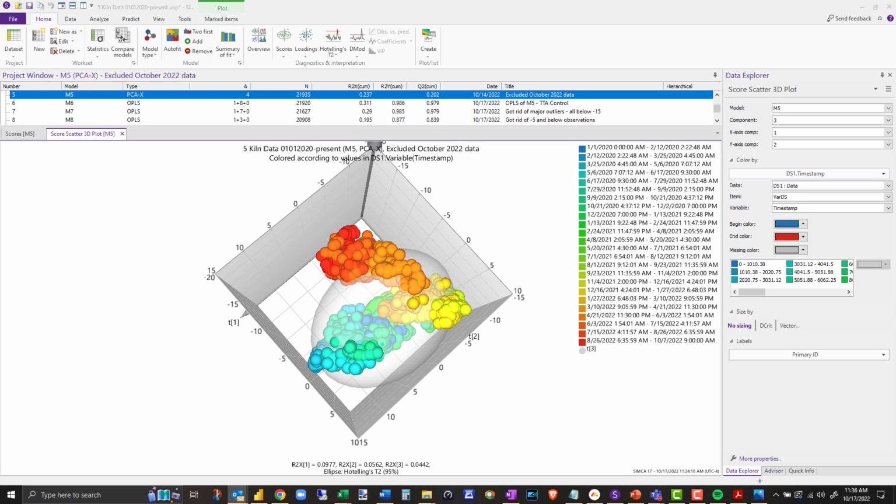Yep. So you're going to lose, as you say, fidelity. You're going to lose some fidelity, but you're not going to lose the information. Right. And that's what we try to do, and I give scan class recommendations. Okay, you have a differential pressure transmitter on a key piece of equipment or a vibration transmitter on a key piece of equipment. Yeah, okay, do that every second. Right? You have a tank that holds several 100,000 gallons of material, and it doesn't move more than a few percentage points all day. Why are you scanning that once a second?